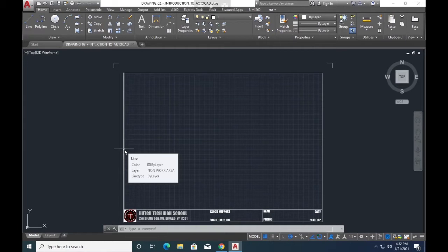The cool thing with AutoCAD is we don't necessarily need to convert guidelines into object lines. We can simply use a command such as trim. It lets us take two lines that might be crossing each other, and instead of erasing that line, it allows us to trim back that line to that intersecting point. I'll explain that to you when we get a little bit closer.